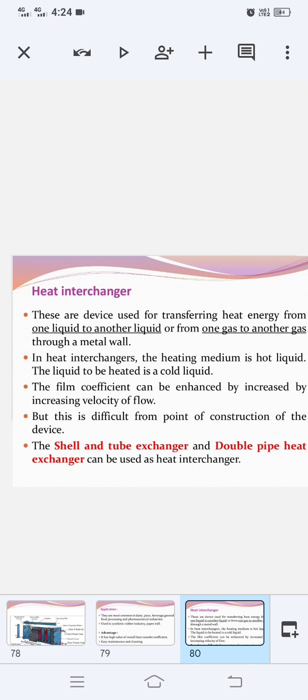Most important parts in the construction of a heat interchanger are the baffles, because they are increasing the surface area of that liquid. The appropriate size of the tube is chosen for the fabrication and the guide rods are fixed to the tube sheets by means of set screws. Baffles consist of circular discs of metal sheet with one side cut away, arranged with appropriate spacing using short sections of the same tubing. Baffles have perforations through which tubes are inserted. The ends of the tubes are expanded into the tube sheets.